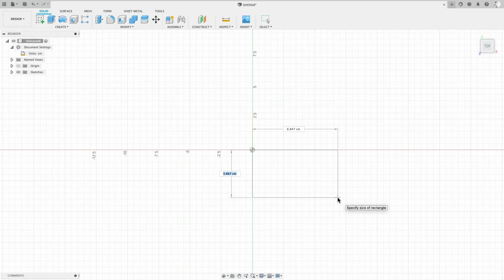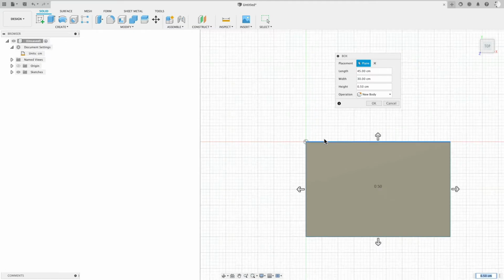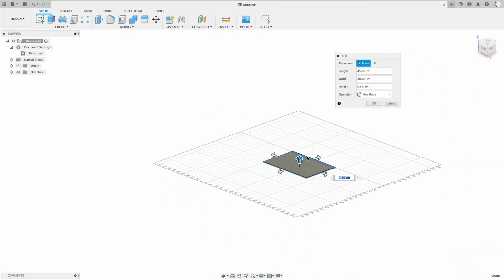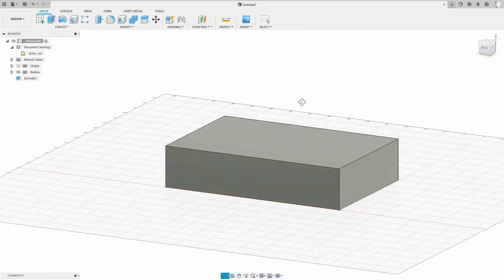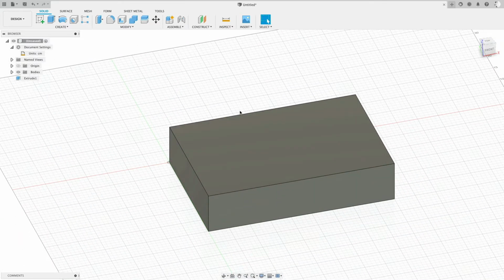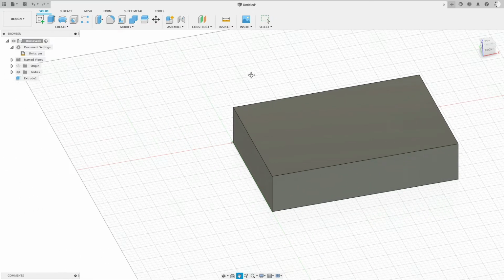And there you can see the dimensions. So what is 3.7 in my case should actually be 30. And then press Tab. And then that one should be 45. And enter. Then we can scroll wheel zoom out, shift middle mouse button rotate, and the height should be 10. Very good. So now we created a wooden block that has 45 centimeters length, is 30 centimeters deep, and has a height of 10. That's 50% of the part.